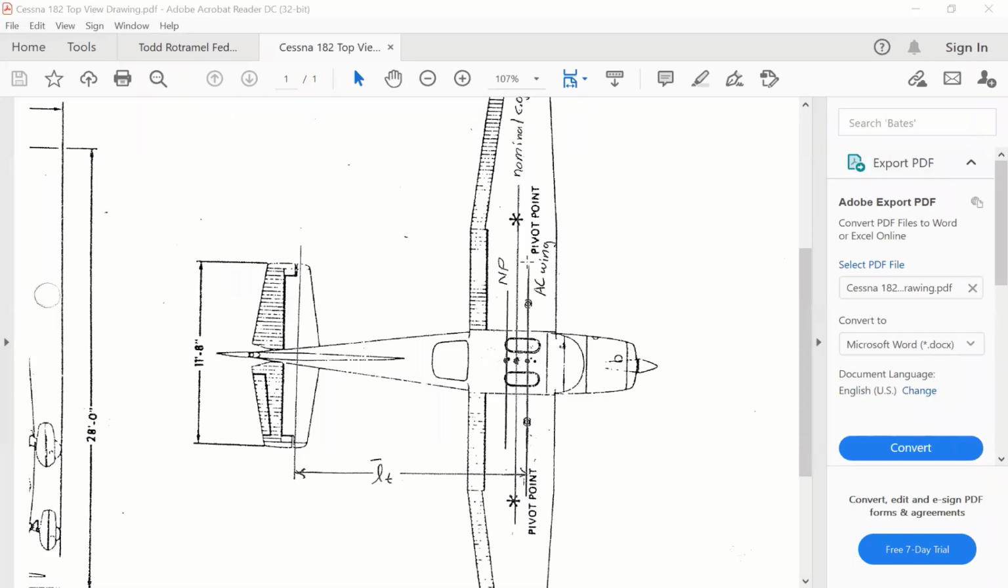So we know the geometry of the airplane. We know the wing span, wing chord, wing location, the location of the aerodynamic center of the wing, the location of the aerodynamic center of the tail. We'll have actual numbers for that. Plug them in these formulas and calculate the neutral point and various other features of the pitch stability of this airplane. We'll find out that this distance between the nominal CG and the neutral point, I think, is about ½ a foot. So it wouldn't take too many heavy suitcases behind the seats back here, or even in the seats, to shift the CG back and cause the airplane to be unstable.